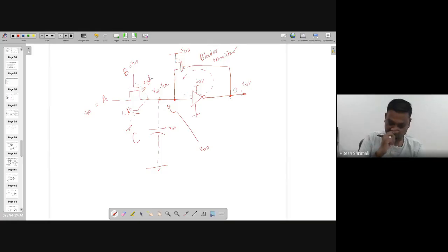This is gate to drain, and on the input side, that is Cox, the biggest capacitance, and on this side there is a capacitance CGD. So all these capacitances altogether are going to be reflected over here, and I'm calling them a big capacitor C, and that capacitor will definitely be the biggest one, coming from the individual capacitors, or you can keep a capacitor bigger than all these parasitics. Then you can find out the propagation delay at this node by the Elmore delay.